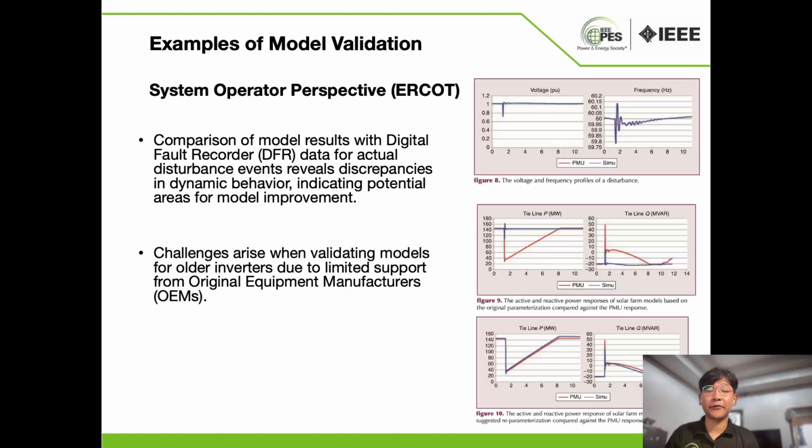System operator perspectives, such as the Electric Reliability Council of Texas, utilize phasor measurement units to validate models. By comparing model simulations with PMU data during actual events, they can assess the model accuracy in predicting power response and identify potential parameter mismatches.